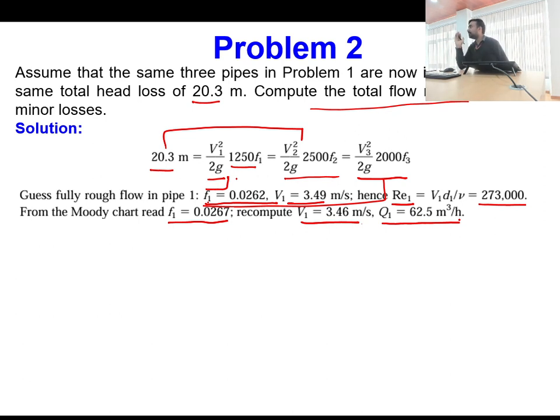When epsilon plus is greater than 70, the friction factor line is completely horizontal and it does not depend upon the Reynolds number. It solely depends upon the relative roughness. So we have the relative roughness known, and from the relative roughness data we are just obtaining the value of friction factor for the totally rough region, for the initial case. Is this point clear?